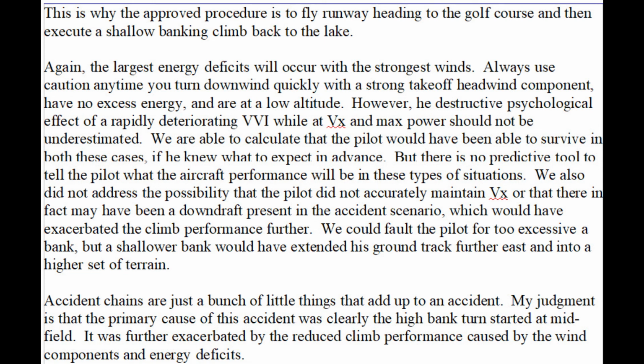We also did not address the possibility that the pilot did not accurately maintain Vx, or that there in fact may have been a downdraft present in the accident scenario, which would have exacerbated the climb performance further. We could fault the pilot for too excessive a bank, but a shallow bank would have extended his ground track farther east into higher sets of terrain.